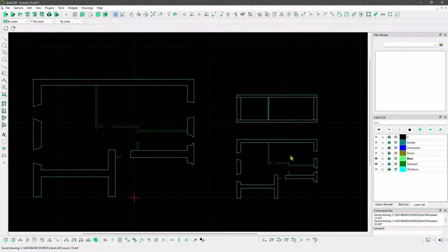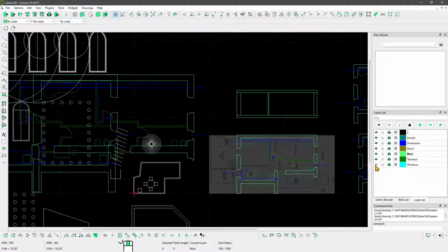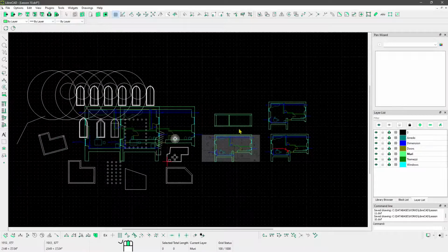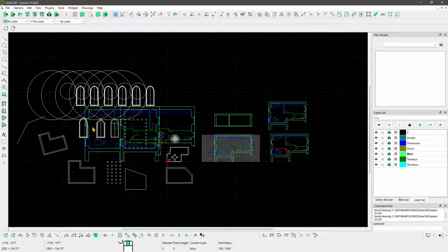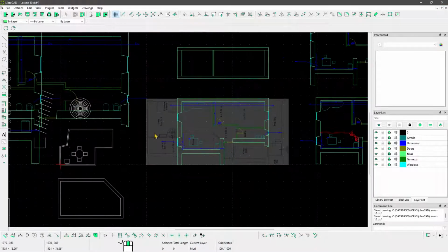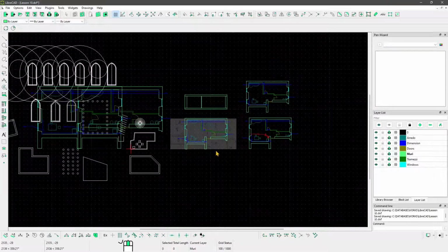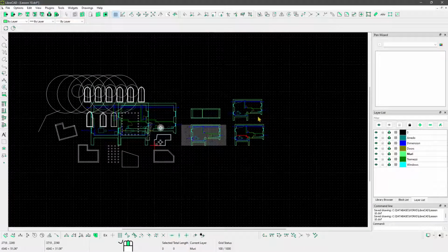Now this one here actually has more objects hidden. You can see how many objects we have here. So well, when you export, like when you save a DXF, it's gonna import basically anything that you may not see, but it's there because it's in other layers. Okay, now also get rid of hatches and tags and dimensions, all that stuff. You don't need it. You may need it when you need to print here, or when you need to use graphic design, but you don't need it for 3D. So get rid of everything that is too complex.